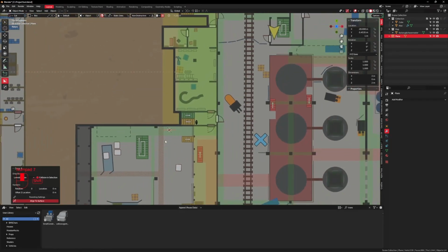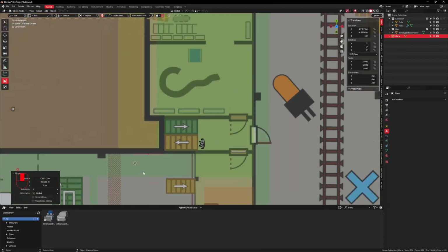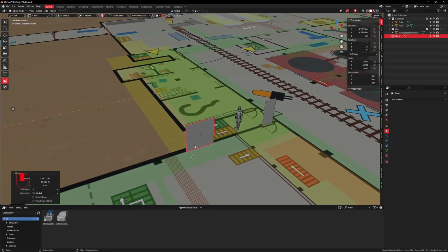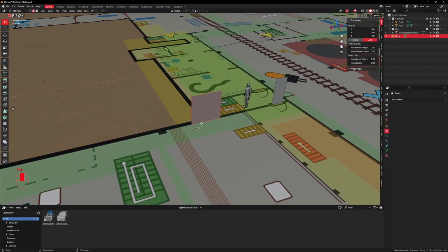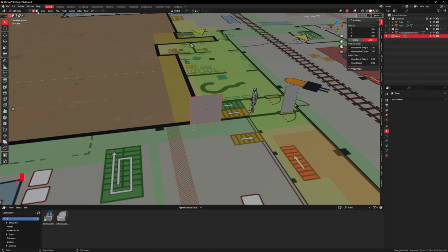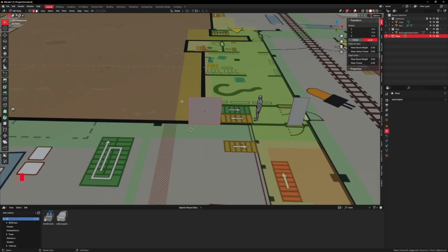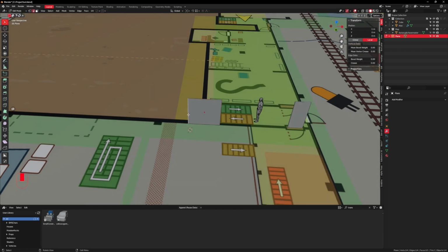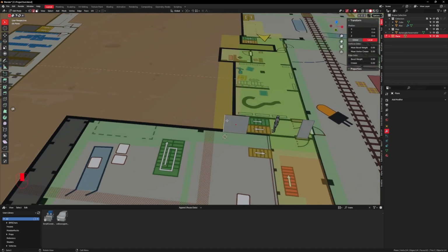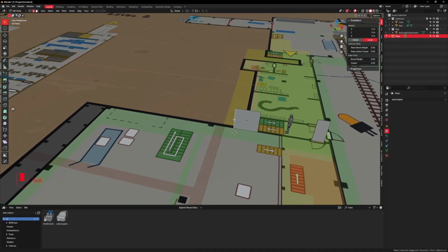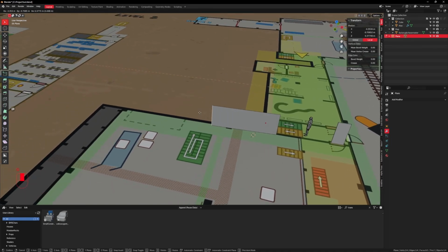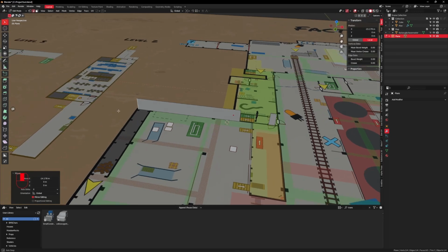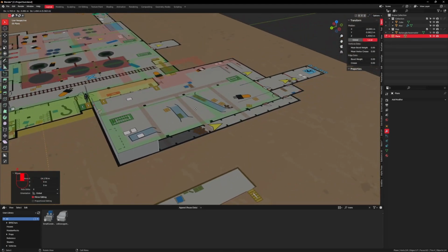Okay. Top-down view, align it here to the reference, and then press Tab to go into edit mode. And when I press 1, 2, and 3 on my keyboard, I switch between the different edit modes. You can see up here in the top left corner which edit mode I'm in. I'm not sure if the 1, 2, 3 thing is default settings, but I think it is. But yeah, make sure you're in edge select, press G to move these verts, and then middle mouse click to lock on to this axis, and just move this over into that corner. Okay. E to extrude, middle mouse to lock on, and click. Okay.